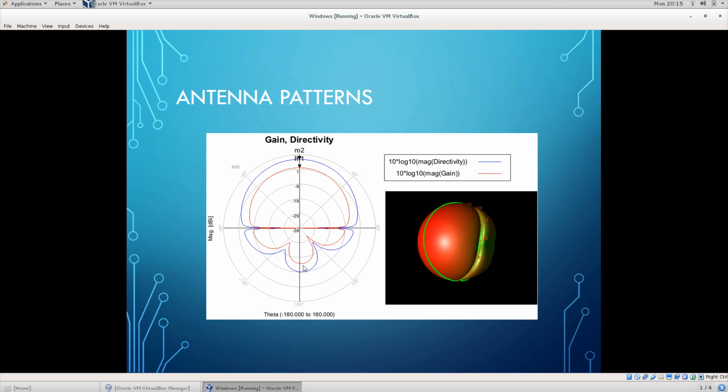The point is that it's not radiating very well this way. As we all know, in log magnitude, if we're 30 dB down, we're about 1,000th of the energy. So we're around 25, so let's just say we're about a 500th of the energy content of the directed radiation up this way. Right? So that's pretty considerable, isn't it?